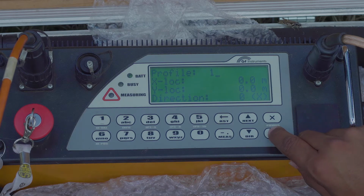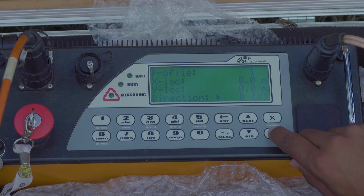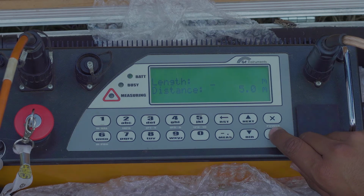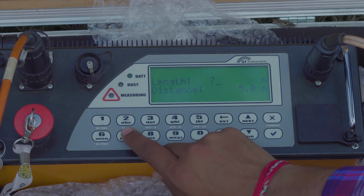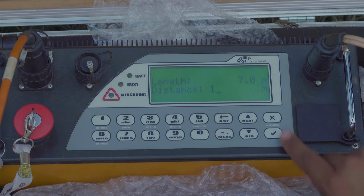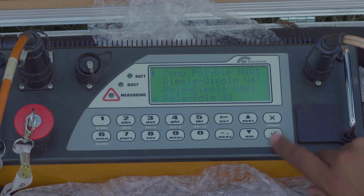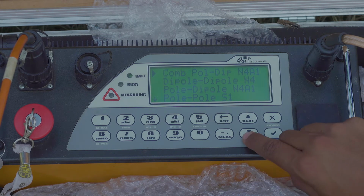We will set the profile number, the X location, the Y location, and we can see that the profile is increasing in the X direction, so we set those values accordingly. We then set the profile length and the electrode spacing. The distance we are setting is the electrode spacing. From there, we then choose the array that we want to take the measurements in.